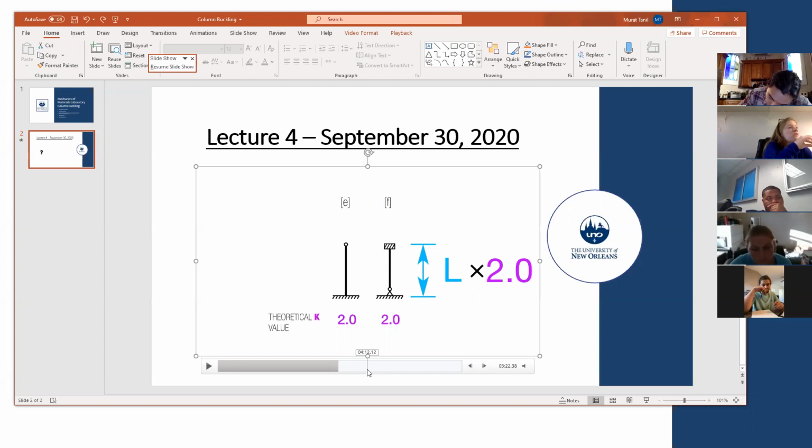And in some cases, you need flexibility. If you're in the seismic zone or if you're in the hurricane zone, you need to give some flexibility to your design. So you cannot assign fixed everywhere. Otherwise, it's going to be a more fragile design. So if you have some flexibility, it's going to move and it will come back to original position because it's going to be moving in the elastic region. Make sense? The first reason is the economical reasons. It's expensive, it's costly to have the pins fixed. Okay.